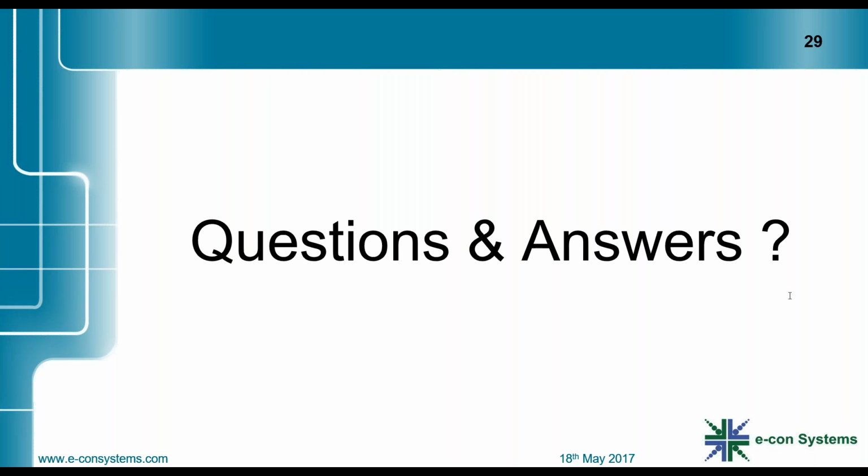Is there any interface for multiple USB 3 cameras to connect to Jetson TX1 on different buses? When customers require multiple USB cameras on the TX1, they can use a powered USB 3 hub, because the power requirement for multiple cameras might exceed the power that can be delivered through the USB 3 port on the Jetson TX1. So it is recommended to use a powered hub. But obviously, when you connect more than one USB camera, you'll get a much lower frame rate. Since we have more than one camera interface, we can use MIPI cameras instead. If you are looking for a long distance camera, that can be customized.